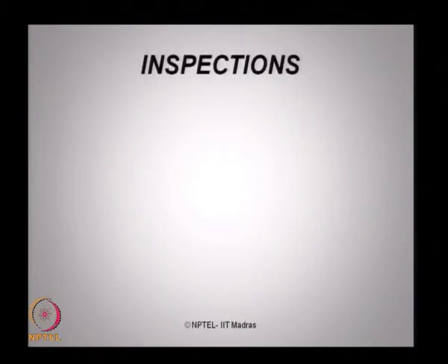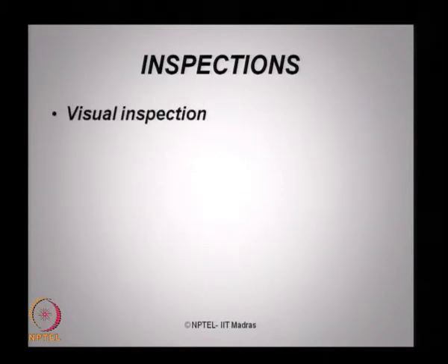The next important feeling people have in terms of improving the strength of concrete or the performance of concrete members in sea environment is the type of inspection which can be carried out to constantly monitor the strength of concrete, its durability and its performance in a progressive manner, and keep on correcting it before it degrades much beyond the acceptable level. Visual inspection is a foremost red line in the inspection methodologies.